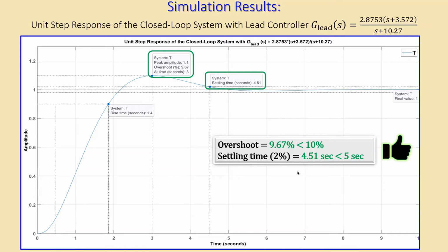You can improve this, of course. You can make also a little bit adjustment in maybe the location of the pole, maybe the location of the zero, maybe both of them, maybe also the gain. You can do many things to make it even maybe faster, also make the overshoot a little bit less. That's all possible. Now I will do that also briefly in the next step in MATLAB real life. So let's also look at that in MATLAB using the control system tuning method, which will be helpful also to see what's actually happening when I change a parameter of the controller.